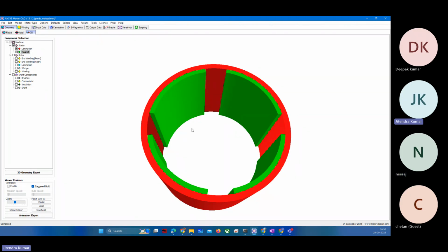Actually, we do not worry about that because it is sufficiently high. The work is temperature dependent degradation. As you increase temperature after a certain point, like 150 degrees centigrade, some portion or the entire portion of these permanent magnets may get demagnetized permanently. So then it will not be of any use.